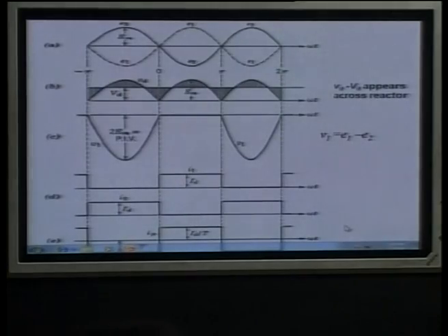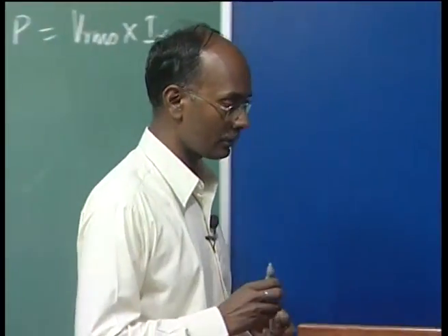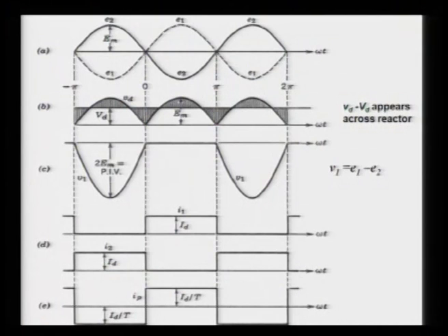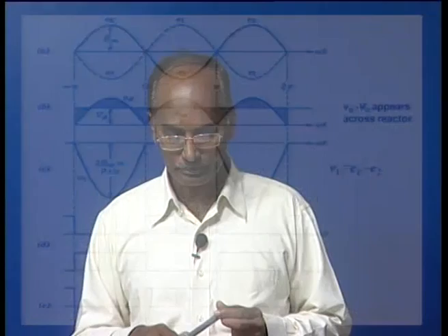That is why in converter circuit analysis we never get a perfect sinusoidal. We have a lot of harmonics, but the fundamental has the highest magnitude and the other harmonics have minimal magnitude. That is why transformers are designed in a special way, so that there is no saturation and losses are minimum, because many harmonics enter the transformer. Similarly, with larger and larger numbers of phases, the waveform will be almost perfectly sinusoidal, and we will analyze the 3-phase circuits.